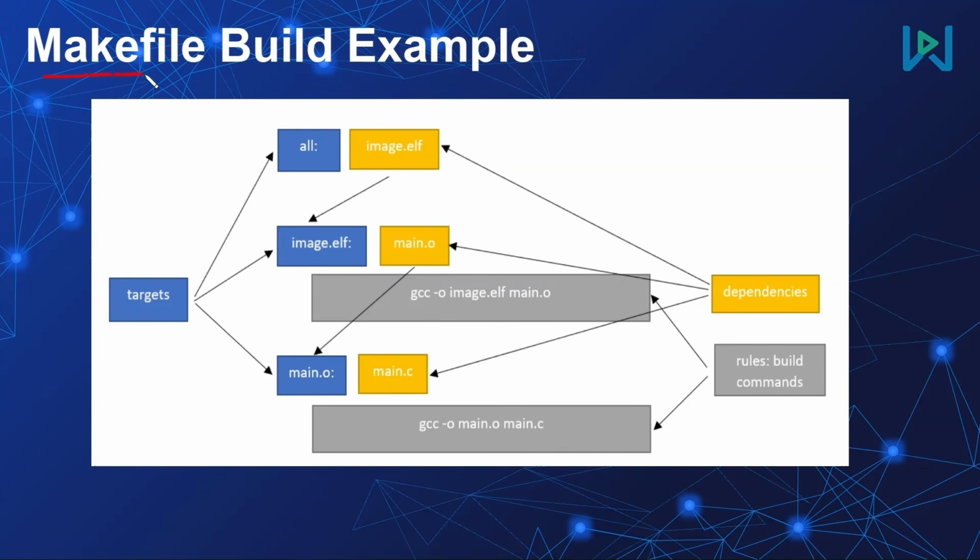This is an example of how we can use the Makefile to automate the flow of execution of the different rules and jobs to compile and generate the final embedded system image. Here we can define a set of targets. Those are considered Makefile targets, and each of those targets will basically represent an output file. So this one, for instance, will represent the output object file coming out of the compilation stage of our main.c.